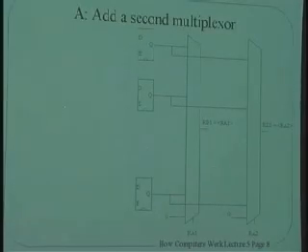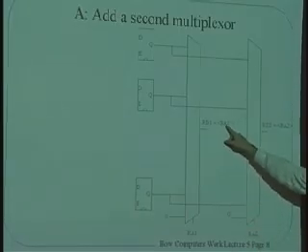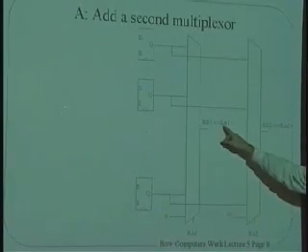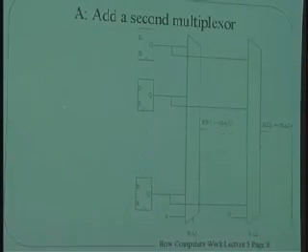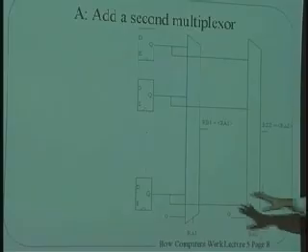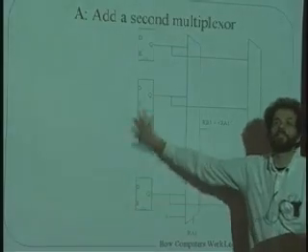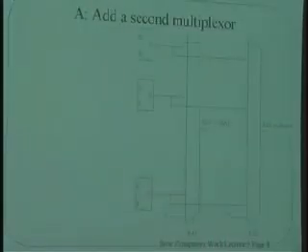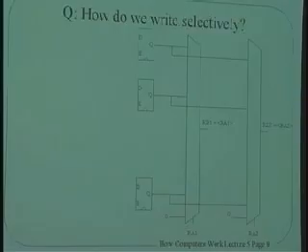Yeah, could you just remind me what RA and RD stand for? Sure. RA is read address and RD is read data. Okay, we're also going to have WA and WD for write address and write data. So that's how we read from these registers. Now, I haven't talked at all about how we get data into them yet. But guess what? There's some blank space on the left side of this picture. And through the magic of PowerPoint, we're going to fill it in.